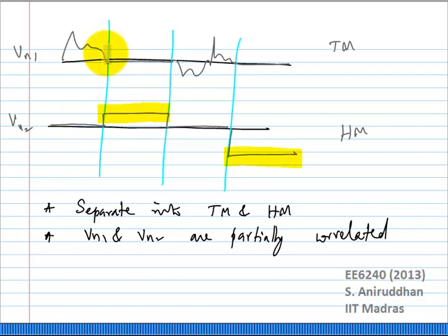Yes, if the RC bandwidth is very wide, the RC time constant is very small compared to the sampling period. Whatever the last value stored, the moment we turn sampling on again, it will discharge very fast. Correct. Agreed.